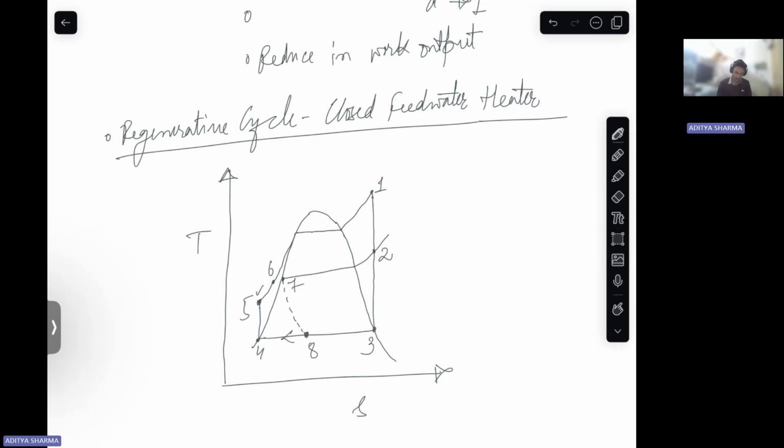And then these two streams come together, and through a pump are again pressurized towards point number 5, okay? So let's say if this is y, this is 1 minus y, so this also will be 1 minus y, so this is y, okay? Eventually here y and 1 minus y means the whole working fluid that started from point 1. So your pump will receive the whole fluid, okay? And this way it will move towards the boiler.